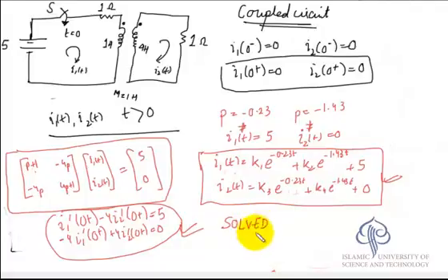So this is the approach that is followed throughout in all kinds of questions. The only trick lies in finding the initial conditions, which is slightly tricky because, like in the previous example, you have to take the voltage across the capacitor and try to find the other initial conditions from it.